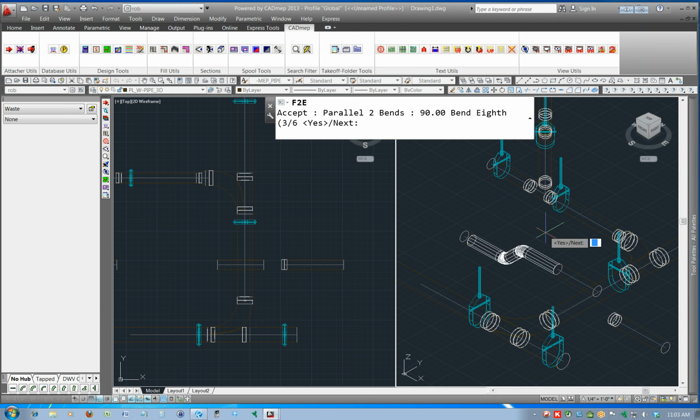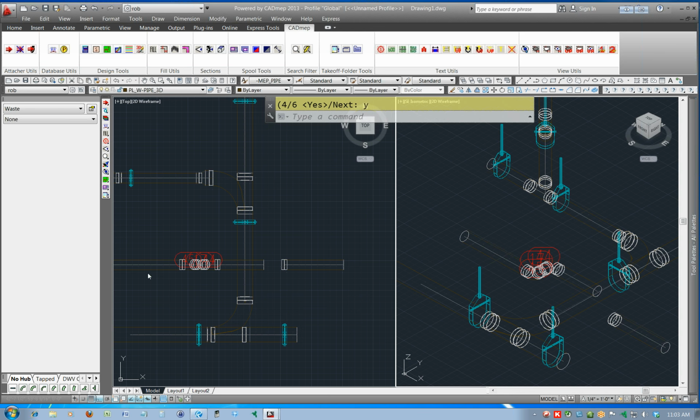Yeah, 6 options now. And you could do the same thing when you want to roll a fitting, like a compound miter, if you wanted to change the elevation and the horizontal position. You do Fill Between Two Ends and it'll connect it for you. But then you do the same on this side, and then you have your offset.